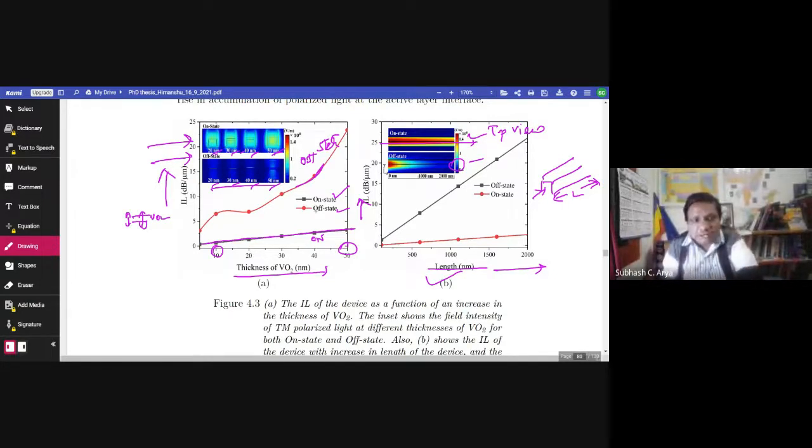absorbed maximally. However, we want to observe what this thickness should be, because we want to optimize it. Suppose we choose 20 nanometers, then 30, 40, 50 nanometers. We observe that the lesser the thickness, the more the absorption. It is not a wise decision to keep the VO2 width high. You can see now the light is less absorbed. It means some light is available.